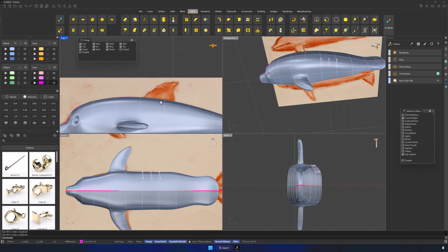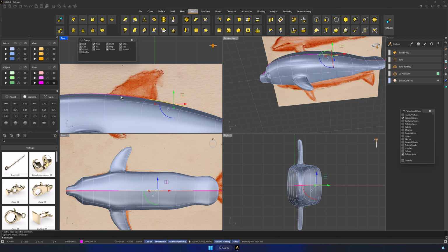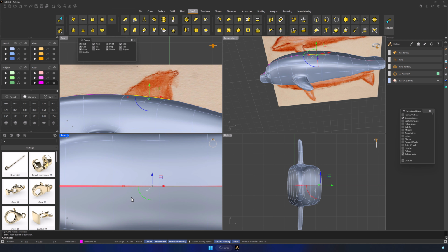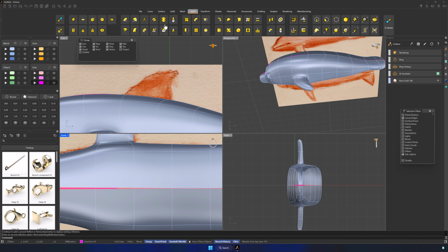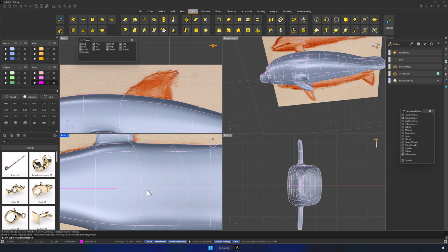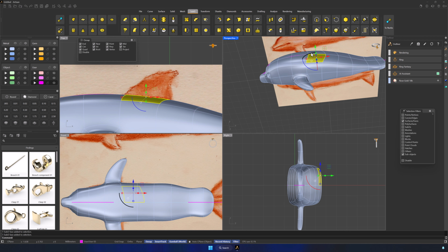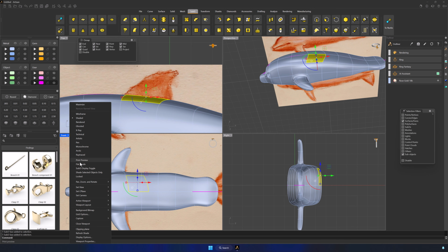For the top fin, first ensure an edge is positioned correctly. Then, disable Reflect by selecting the model, clicking Reflect, and choosing Remove existing reflect symmetry in the command bar. Switch to the back view to access the top side of the dolphin.